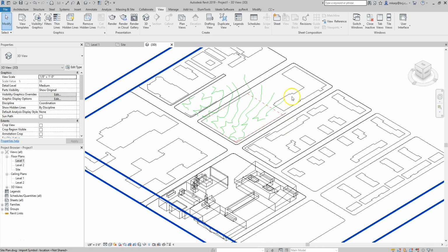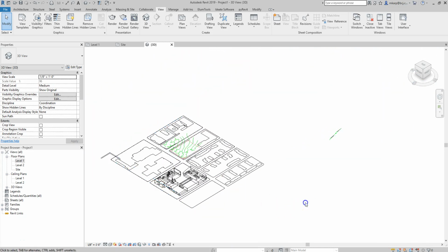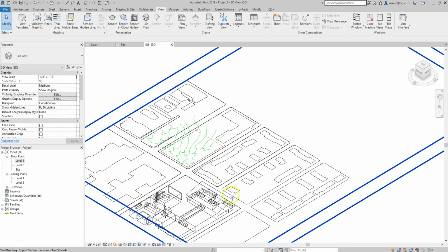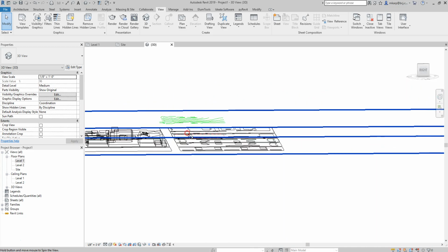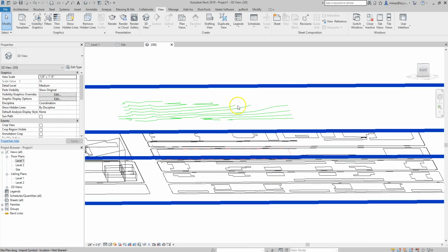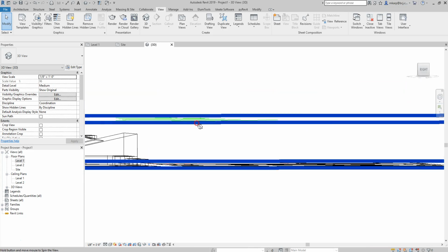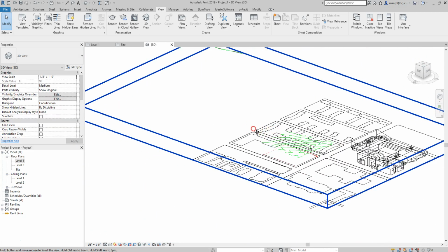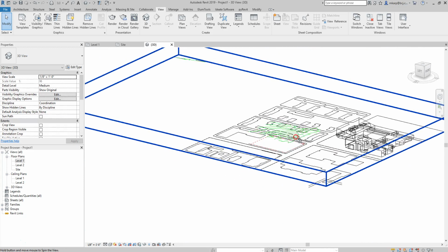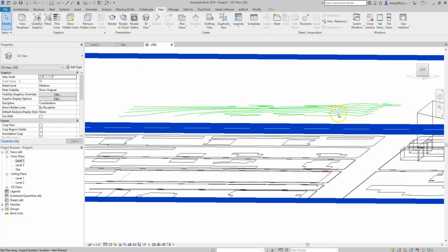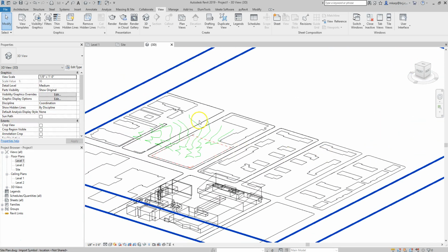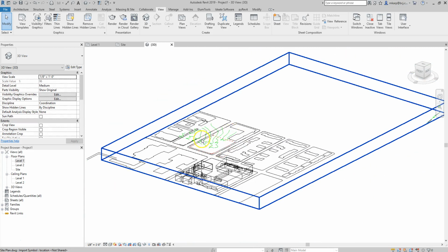And what this does is it shows you what you have in 3D. So we have a cube over here, and if I hold down Shift and rotate by pushing in my scroll wheel, you'll see that our topography is actually three-dimensional. It came out of AutoCAD at the right height off of sea level. So right now, 0, 0 is where everything was placed in. However, this topography is coming in around 80-something feet above sea level, which is good, because that's where we're going to start with our topo surface.